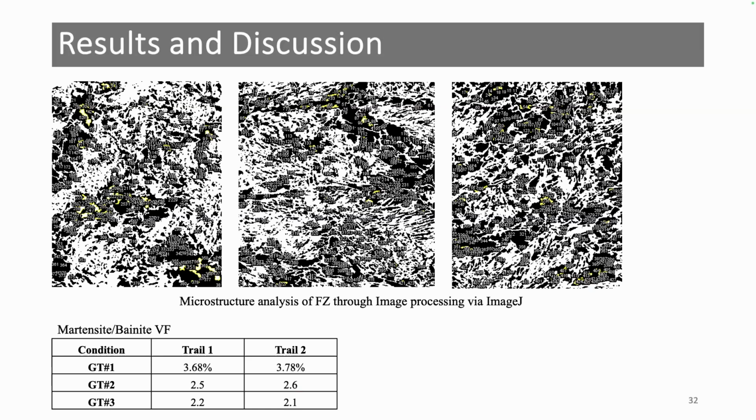As we said in the previous study, this is similar. When we increase the heat input, then the size of the fusion pool is increased, and this affects the cooling rate. Therefore, when we increase this heat input, the cooling rate is decreased. Therefore, if this one is a martensite, then the amount of martensite will be decreased with decreasing the cooling rate.